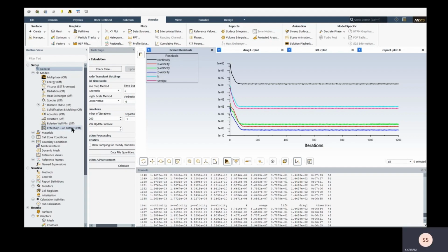So now we'll work on the simulation part. This will be carried out in ANSYS Fluent. And now what you see is the workspace. Under the Fluent workspace, we have to choose what type of simulation model we are going to work on. Since we're working on the aerodynamics of an airfoil, which involves fluid flow, I mean air flow, we'll be using the viscous SST k-omega model.